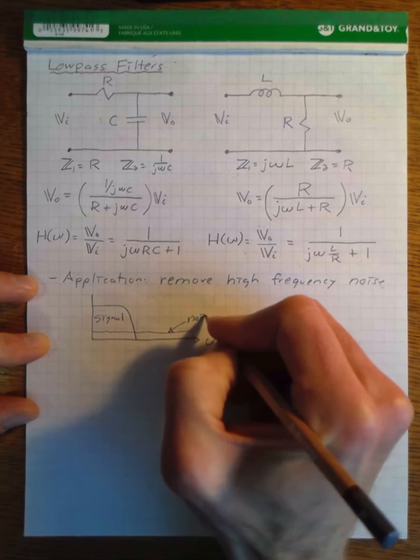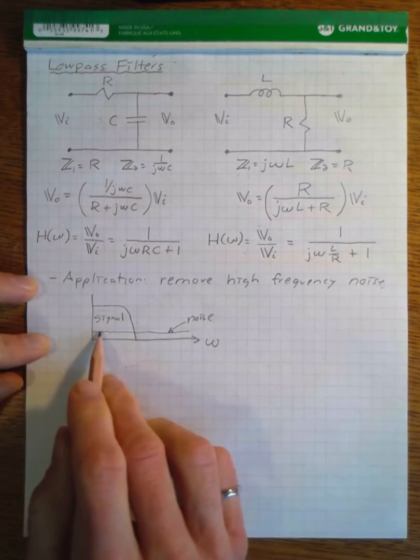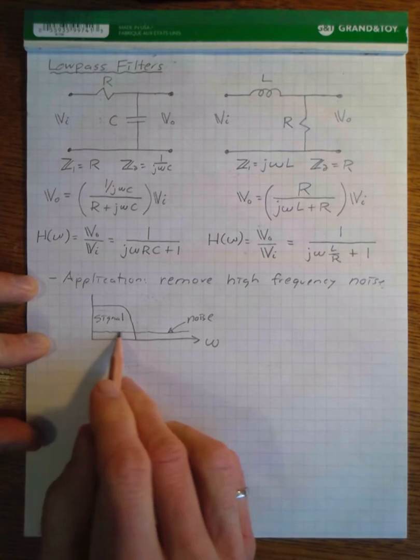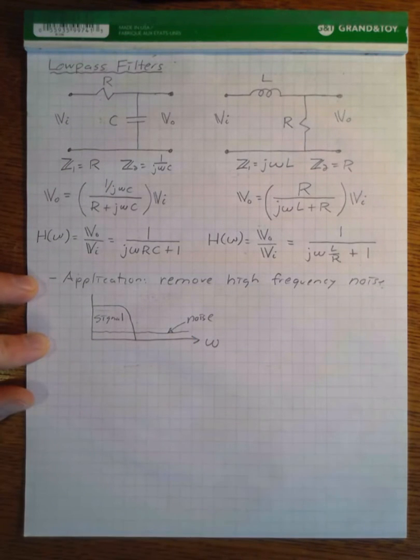However, often the signal will be corrupted by noise that has low frequency components, but also very, very high frequency components. And this noise can come from the thermal noise of our electronics, just random electrons bumping around, or if we're using some sort of digital to analog converter that has some quantization, this noise could be caused by the signal quantization.